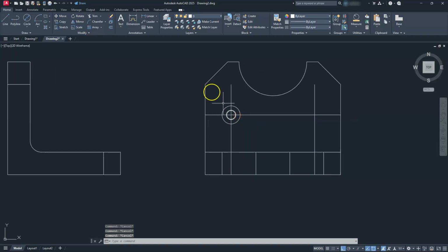All right. I can go ahead and copy this. So I'll go to copy, and once again, if I didn't know that, or if I didn't see it symmetrical, because I could mirror this across, but just to make sure that I'm using everything right, I'm going to go ahead and copy this. Once you're done selecting, hit the enter button. Go from that center to that intersection. Oh, looks like I hit the escape button too quickly. Let's go back to copy, select my objects, hit enter. Click on this center here, and then I'll click on where it perpendiculars, hit the escape button. And then the last thing I have left to do is delete these lines here.